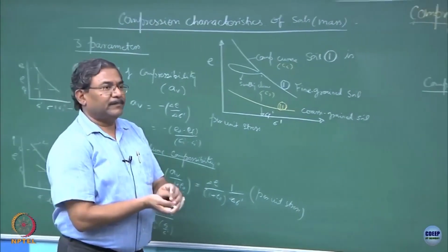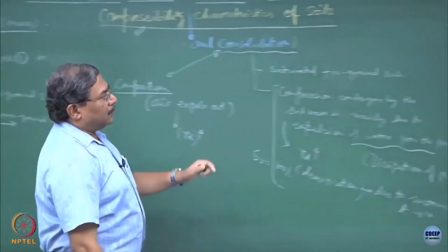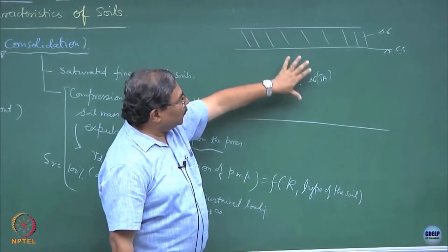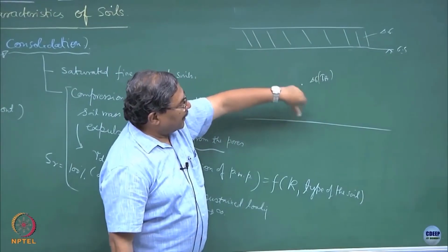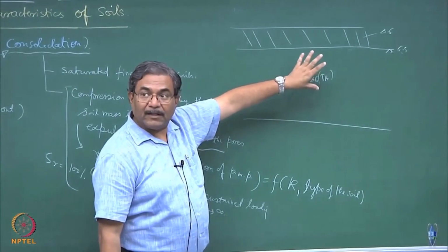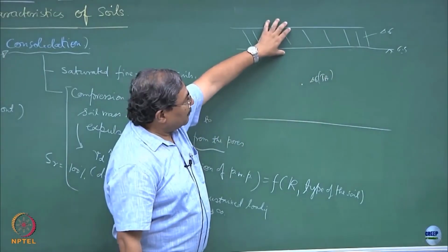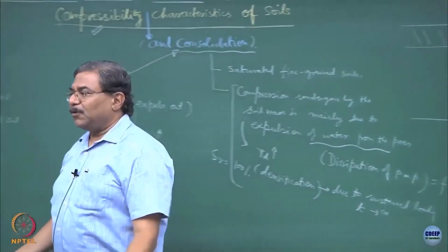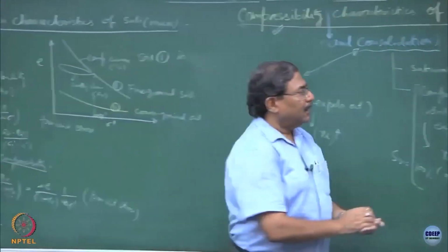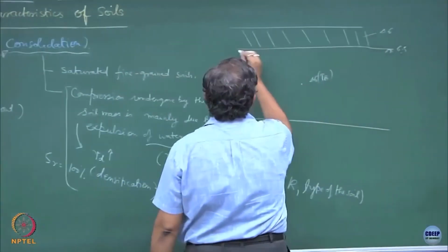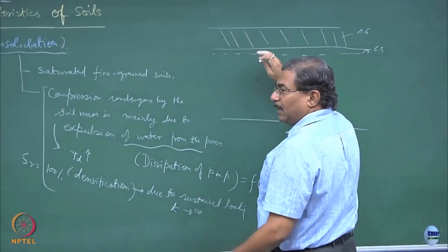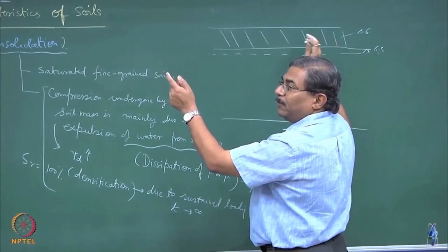Is this part okay? So even if I take the soil and compact and create an embankment which is going to sit on a marshy marine clay type of a soil which is highly compressible, once this system is formed, initially there is no problem, but in the due course of time what you will observe is that this whole system will start slowly and slowly settling down, and most of the time these settlements are not very uniform.